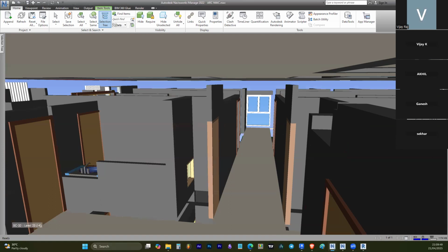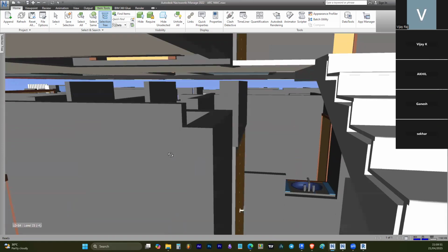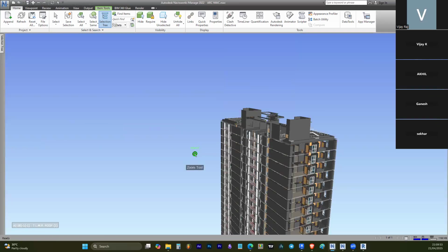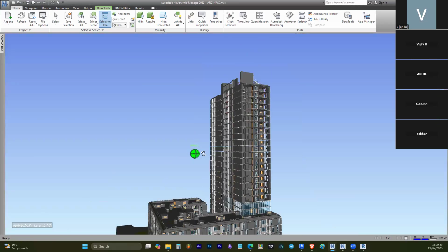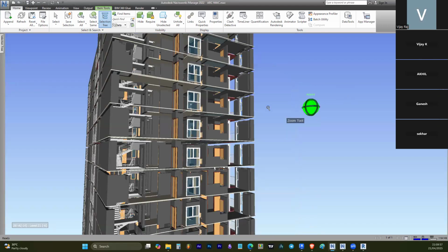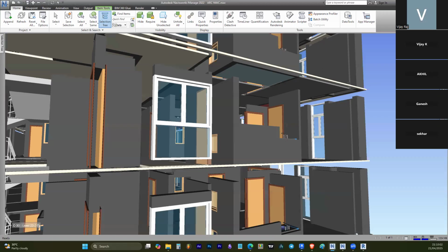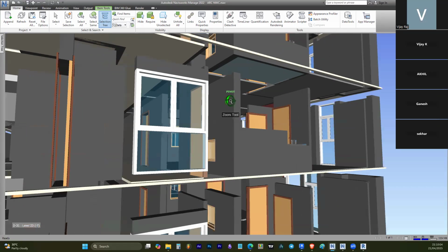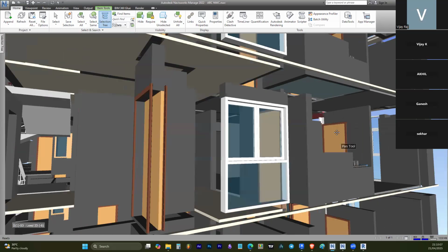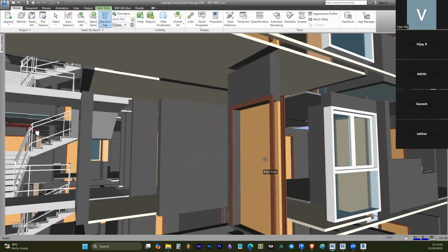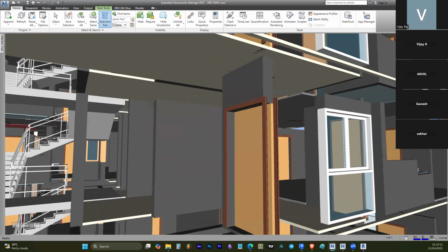This is the orbit tool where we orbit the model, right? Like using the Shift key, we will be doing the orbit. And this one is the pan tool, and this one is the zoom tool. The pan tool, also the mouse center wheel, we can pan immediately, or else if we go to this area, you can get the pan tool. So this is the wheel, the navigation full wheel. This wheel will help you a lot of times.